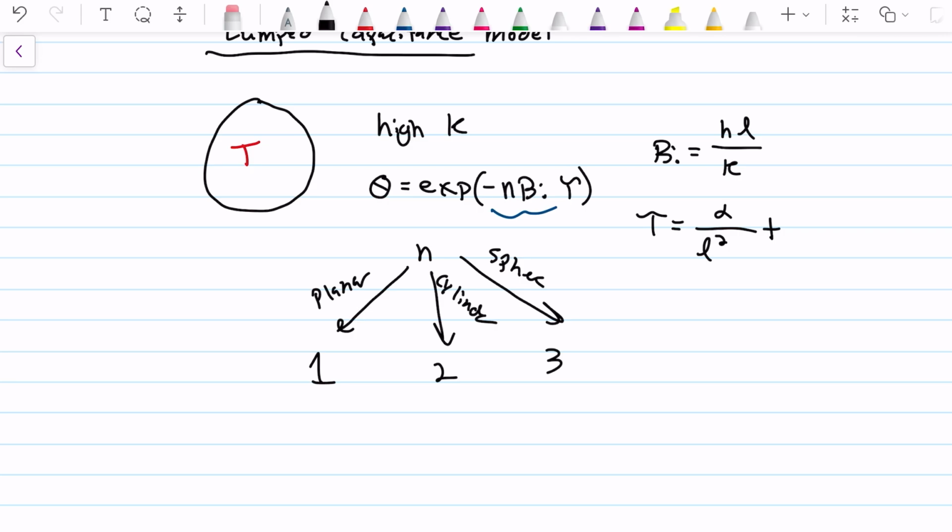And then if we have a constrained problem, we should be able to solve for something we're looking for. Let me also define dimensionless temperature, which is the temperature at some time t minus the ambient temperature, all over the initial temperature minus the ambient. So with this setup, this really should be enough to solve any of the lumped capacitance questions.